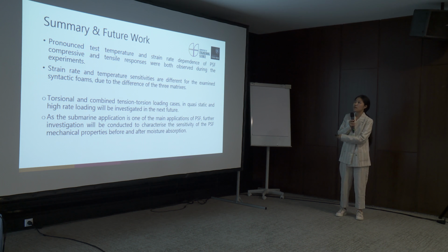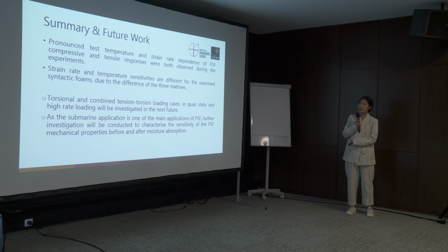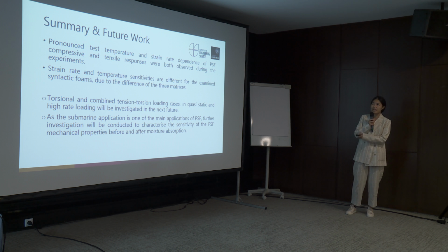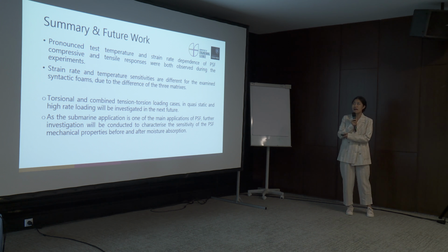So in conclusion, pronounced test temperature and strain rate dependence of the polymeric syntactic foams' compressive and tensile responses were both observed during the experiments. The strain rate and temperature sensitivity are different for the examined syntactic foams due to the difference of the three matrices. So in the future, we will investigate the properties of the syntactic foams under torsional and combined tension-torsional loadings, and we will also characterize the sensitivities to the moisture absorption effect on the polymeric syntactic foams.